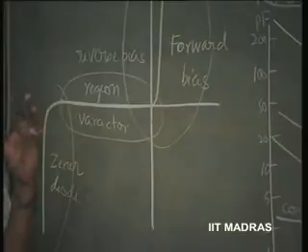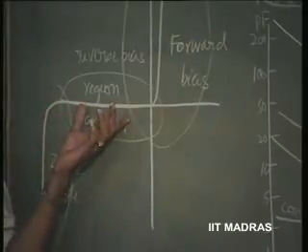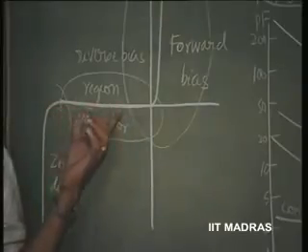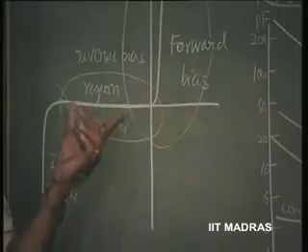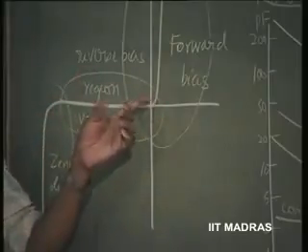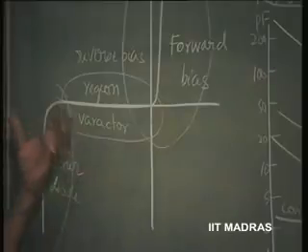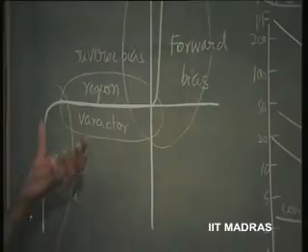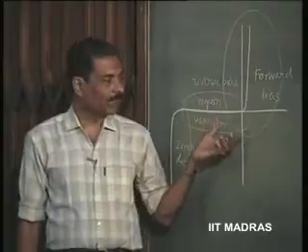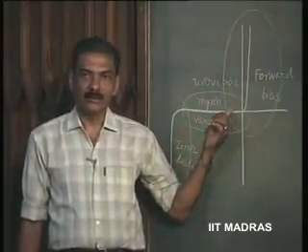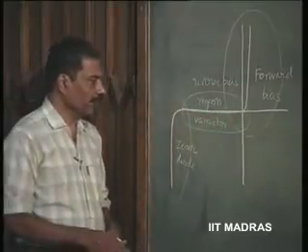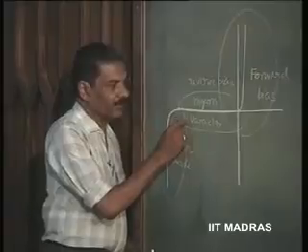But therefore you have to remember that power diodes, okay, sometimes should not be really used for high speed applications because the capacitance of it is really very high. So, that means high frequency rectification, you should not use conventional power diodes which are used for 50 hertz. This is the normal confusion that exists. For rectifying a high frequency waveform, we must never use a power diode because it is going to still conduct, okay, because of the capacitance. Therefore, this kind of thing we should be very careful about.